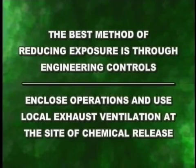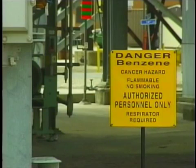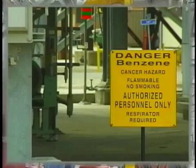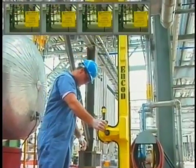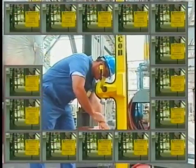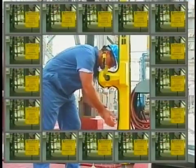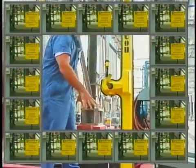Enclose operations and use local exhaust ventilation at the site of chemical release. If proper engineering controls cannot be effected, respirators should be worn. A regulated marked area should be established where benzene is handled, used, or stored, as required by federal or state regulations. Post hazard and warning information in the work area. Wear protective work clothing. Wash thoroughly immediately after exposure to benzene, before you eat or drink anything, and at the end of your work shift.